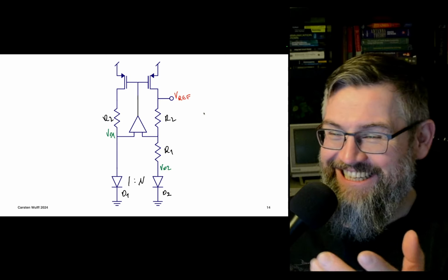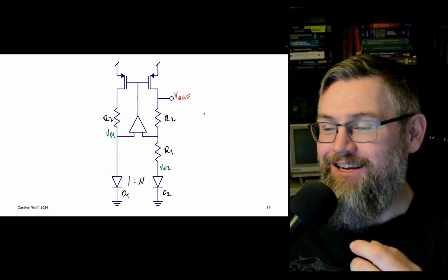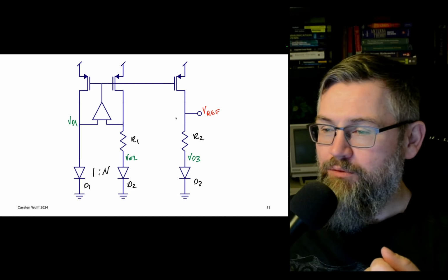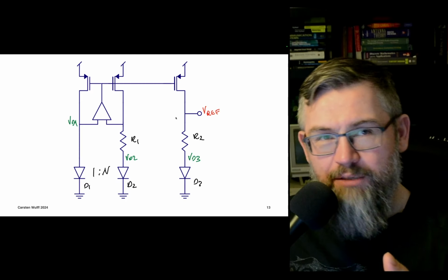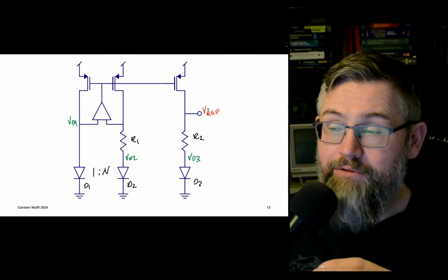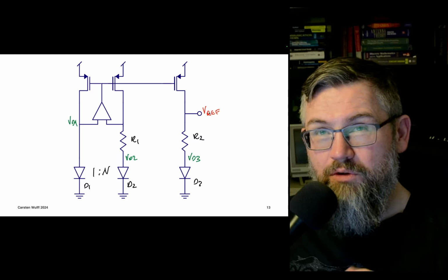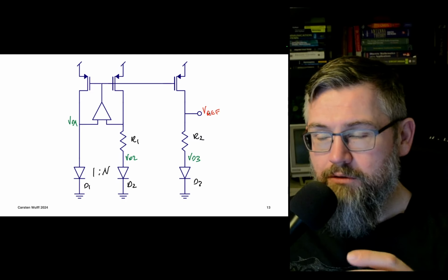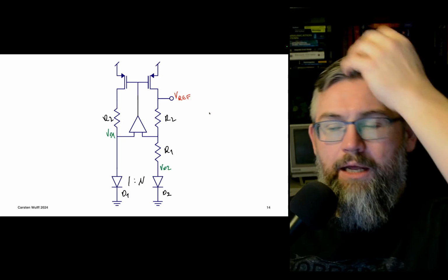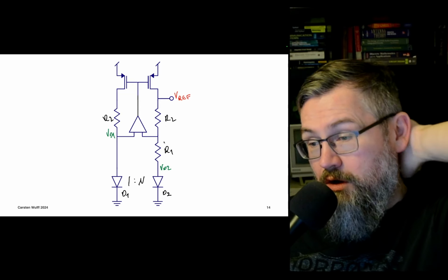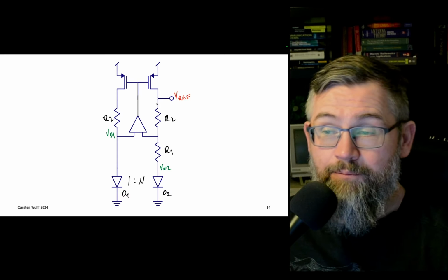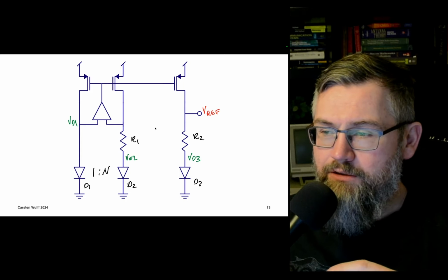Cool, right? There are many ways to combine these two voltages. If you have a lot of headroom, if you're running at 3 volt, for example, or actually both of these need about 1.5 volt to operate, because the reference voltage here is going to be a bit higher than the bandgap voltage, around 1.2 volts. And that's just inherent in this structure. In the case of here, we'll have 1.2 volt coming out, so it's roughly the same thing. Here we're just stacking it. We're basically doing exactly the same.